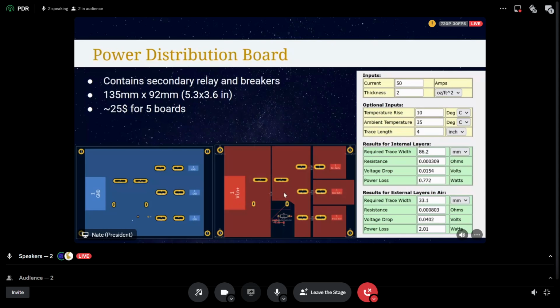It goes from the relay into the 3 different breakers for the 3 different motor controllers, and then we have this circuitry here where we'll just put a wire from the Teensy, soldering straight onto here, and all software is going to need to do is assert or deassert that signal, and it'll shut this relay on or off.